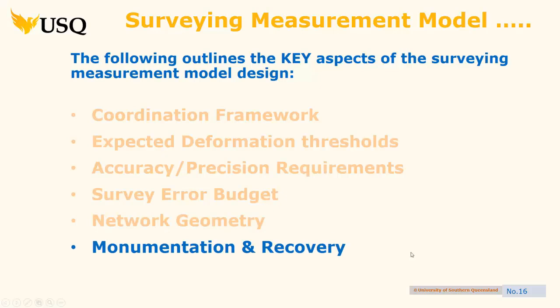And monumentation and recovery. Is this something probably those who have a lot of field training would actually be more familiar with, right? But it's something that students find a little bit hard to picture, because you actually haven't had to build monuments. And there is an art to that. If you go on to, I think I've got some in the study book, the US Corps of Engineers, they've got like 30 pages just covering the type of monuments that you should be building. It's including material, how you test them, things like that. You let them settle.